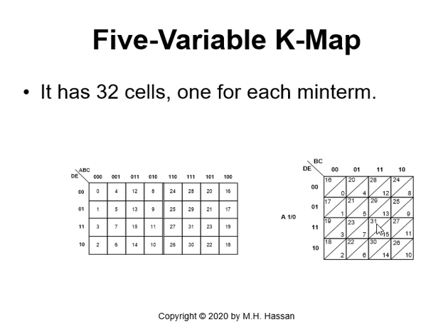So this is one way to do it, or we can do it this way. There's a third way. We can ignore the A. We can have 2 4 variable maps, 1 for D E B C when A is 0, and 1 for D E B C when A is 1. Then when we find the terms, we use Boolean algebra where we can simplify for the A variable only. So this is another approach which I'm not really listing here, but it could be used. So we have 2 4 variable K maps, 1 for A is 0 and 1 for A is equal to 1.